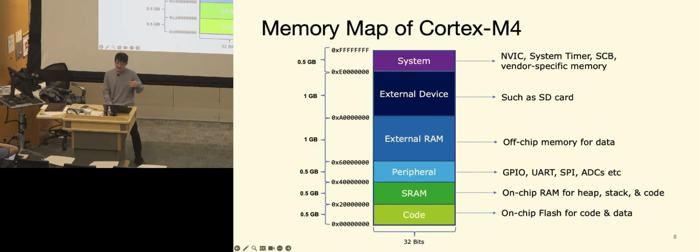Among these memories, remember in total we have about 4 GB of address space available, based on the 32 bits of the address allocated to the 32-bit buses. These spaces are pre-allocated for different vendors to use with a certain amount of memory.